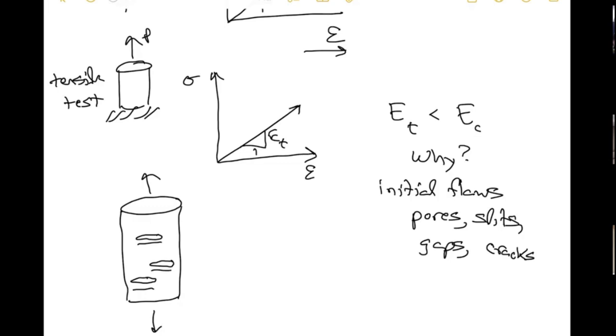But if you push it, that surface is going to close, and now there's going to be traction on it. And so that is now going to be stiffer. You can always think of a body as made up of a whole bunch of springs. And if a surface comes together, now suddenly there's more resistance. So there's an additional spring in there.